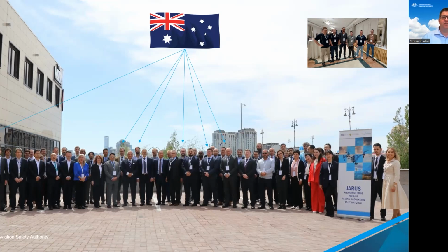Everything I've said about SORA though, it's true to say that it's not without issues in Australia. As I mentioned, we have a big country. We don't have many people. And that actually creates some issues. One of the major issues we get is that we have a lack of data, the data that we need to leverage the quantitative elements of SORA. Related to the lack of data is the fact that we have a significant number of crewed aircraft in Australia that are not equipped with electronic conspicuity devices. Not only does this impact our ability to correctly categorise initial air risks, but it also impacts the ability for BVLOS operators to meet the detection component of the SORA tactical mitigation performance requirements.